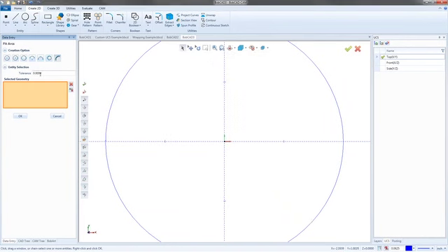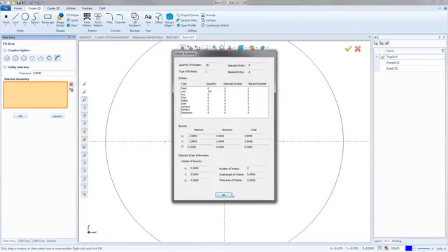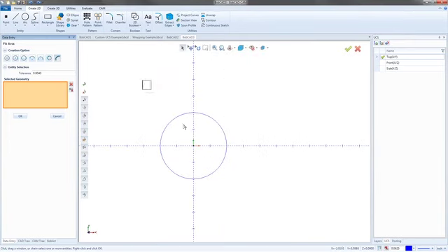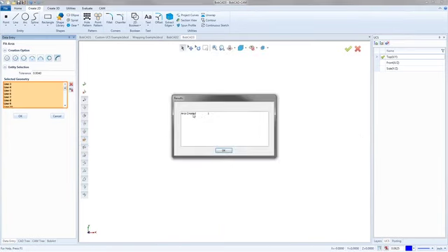So right here, I'm going to change the tolerance. I'm going to drop it to 4 thou. Then I'm going to hit undo 1 time so we go back. If we look at the summary, we have 141 line segments. Then I'm going to drag a box over the whole part and hit OK. Now we'll see it says arcs created 1, but it doesn't tell us about the lines, if it did fix any lines or if it didn't create any lines.